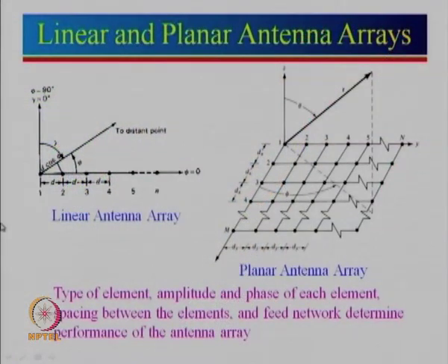However, if I use a directional FM radio, I can get a much better signal. Still, majority of the time we don't use a directional FM radio; we use an omnidirectional one. But with a directional antenna, one can get much better quality, because you know where the FM transmitter is. If we need a very high gain, then we can use arrays of these antennas.